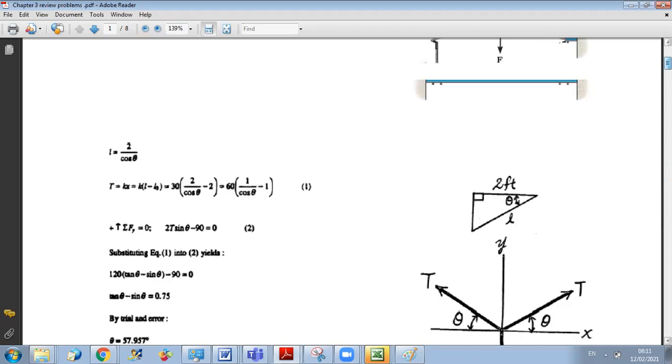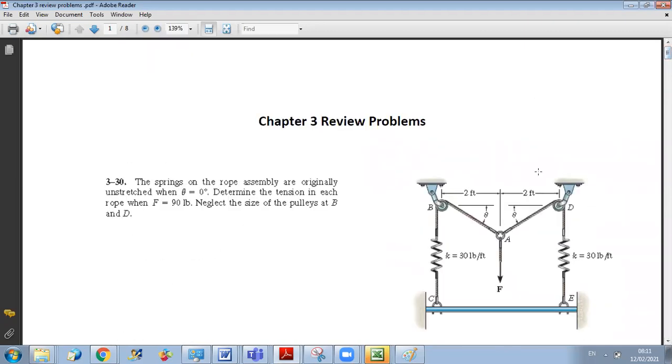Whenever you have an equilibrium problem, try to find what is the point by which pass the different forces. So here you can see that A is the point joining the forces of the problem, which are the force F, which is given. Okay, so since you know something here, you know the value of F. And what is your purpose? Your purpose is to define the tension in the rope. Okay, and the tension in the rope is related also, it's a force exerted on it. So in order to find the tension in the rope, you should write the equilibrium equations at point A.